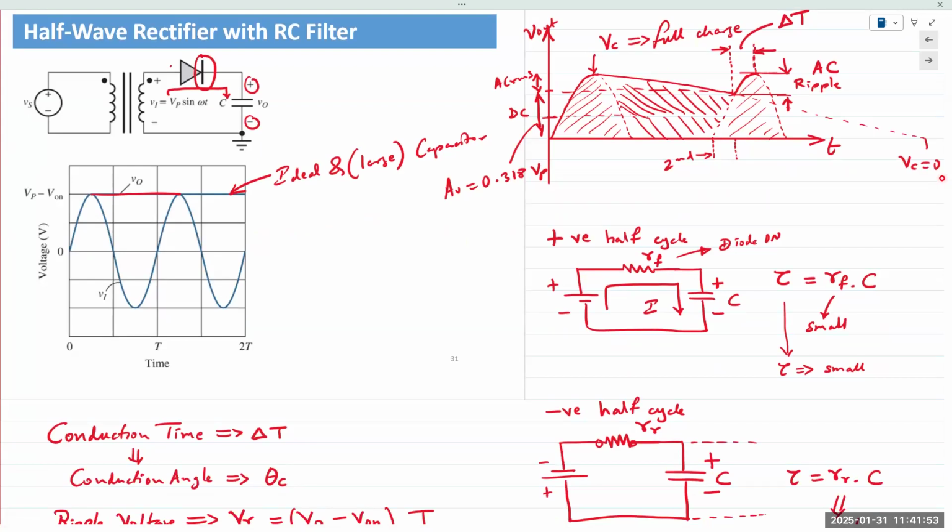So because the capacitor is not, it's not ideal, right? So it's not a flat line. Going back to your point, as you said, it's discharging slowly. But if it was ideal, it wouldn't discharge at all. It would remain a flat line. So it still leaves behind some AC component. And this is completely exaggerated. The size of that peak where it's still empty, like right here, this is empty portion, right? That's that empty portion. That is very small compared to your output. Typically it's in millivolts compared to like tens of volts. Okay, so it's very, very small.